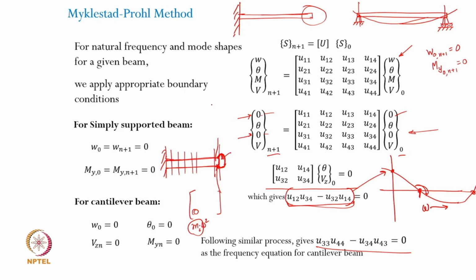Okay. If you can formulate and understand the geometry here properly, and this mass is distributed reasonably in a longer length, then you can also assume this to be a separate segment. Okay, but then that segment's flexural properties will have to be properly evaluated and used as the last segment. Okay, and then its own mass distribution can be lumped at the end, and that is how you need to make use of these.